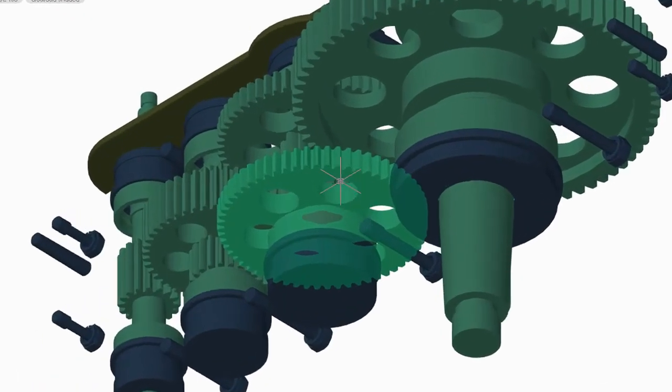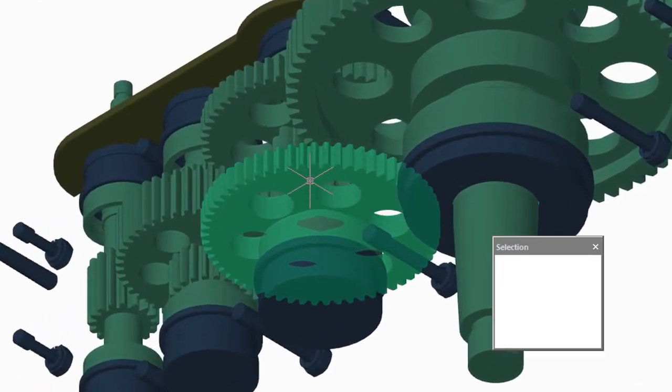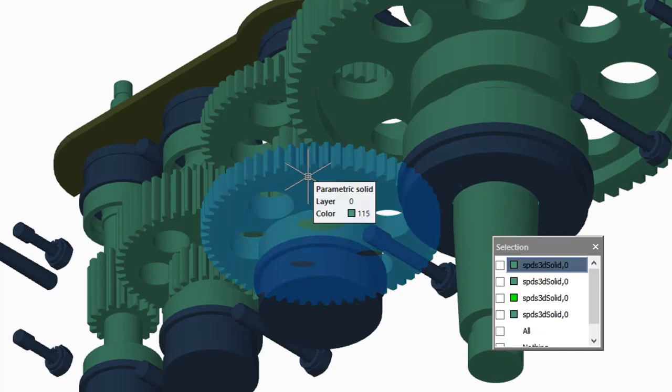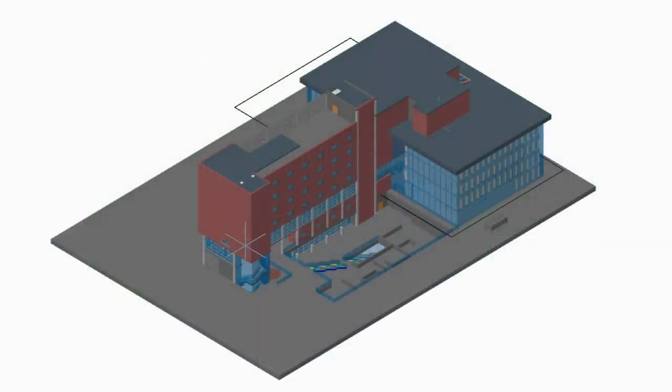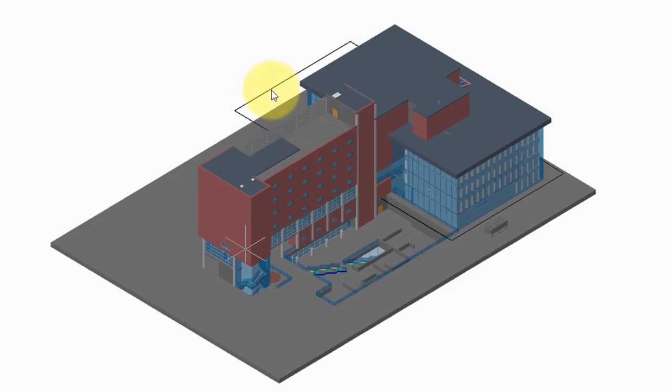When you select a 3D object, it now turns transparent, so you can more easily see what you're working with. Also new in nanoCAD Plus 20 is the bounding prism. To prepare to show you how it works, I've drawn a polyline around part of this imported IFC model.